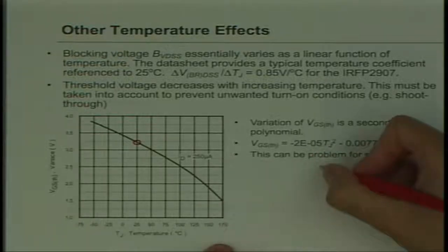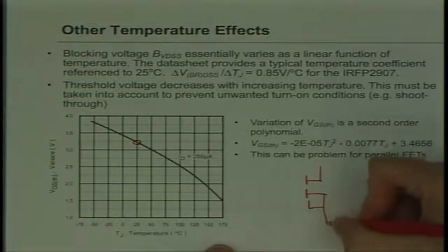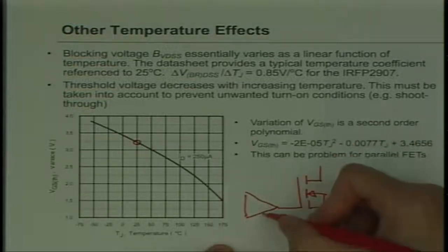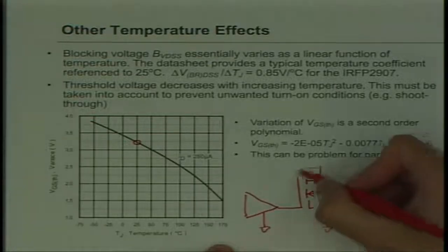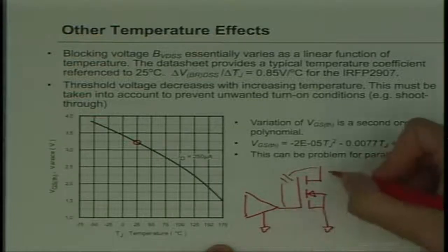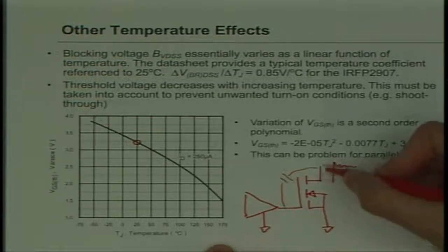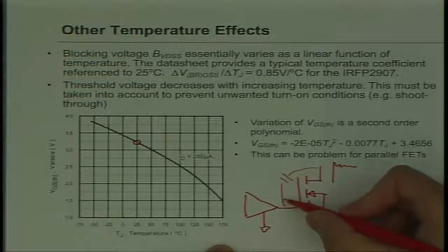And the problem here is that if your FET, I'll quickly draw a FET here, and I have some kind of a gate driver driving it. All right, this is ground, this is ground. I've got this capacitance from the drain pulling, so as this voltage goes up and down on the drain, it's pulling on the gate, and this is rising voltage when it's supposed to be off, right? So as the FET's turning off, this Miller capacitance, gate to drain capacitance, is trying to do the opposite. It's pulling the gate up.